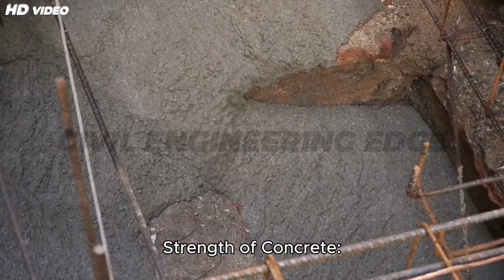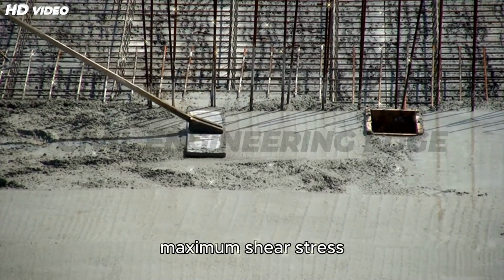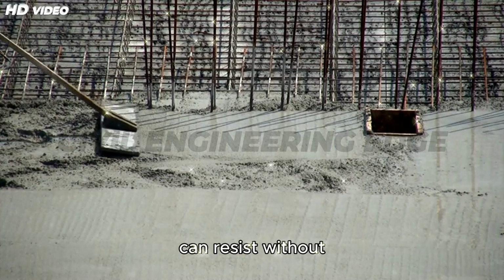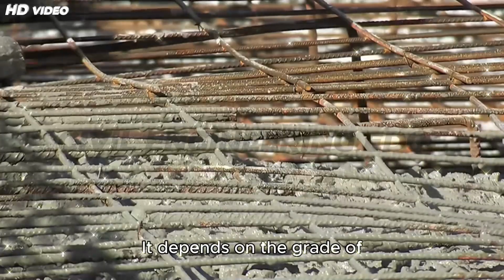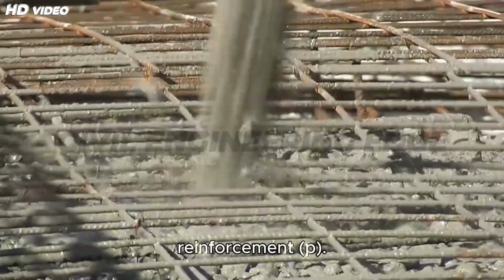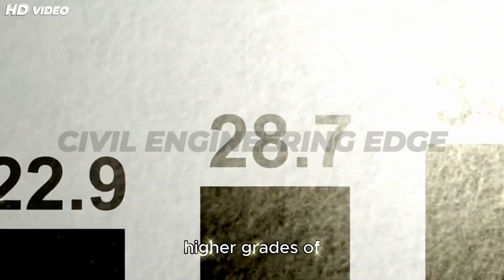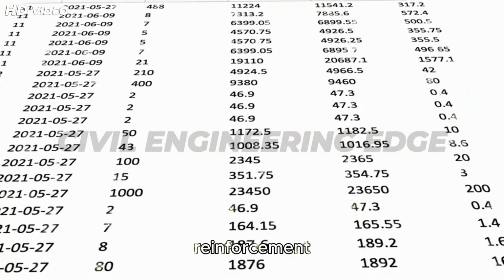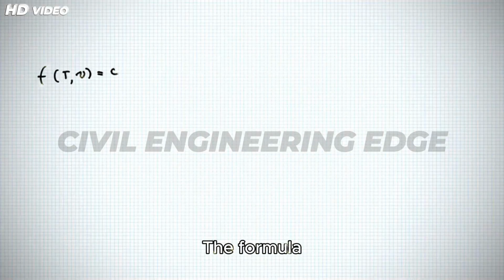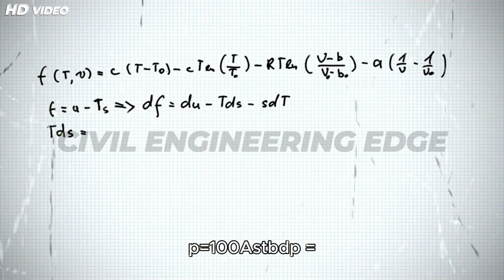Design shear strength of concrete. The design shear strength of concrete, denoted as tau c, is the maximum shear stress that concrete alone can resist without shear reinforcement. It depends on the grade of concrete and the percentage of longitudinal tensile reinforcement p, according to IS 456:2000, Table 19. Tau c values increase with higher grades of concrete and reinforcement percentages. The formula for calculating p is p equals 100 Ast/(bd), where Ast is the area of tensile steel.